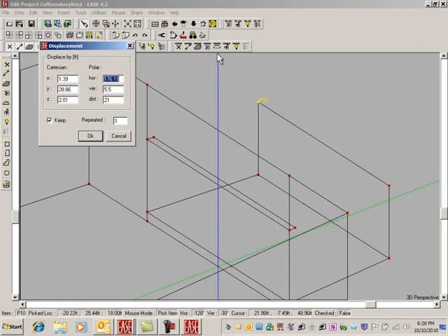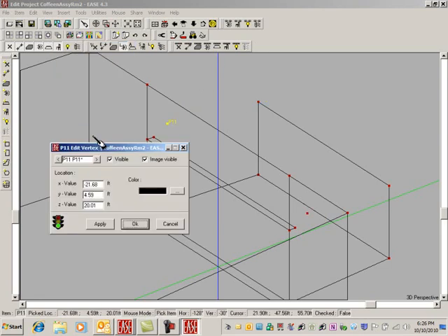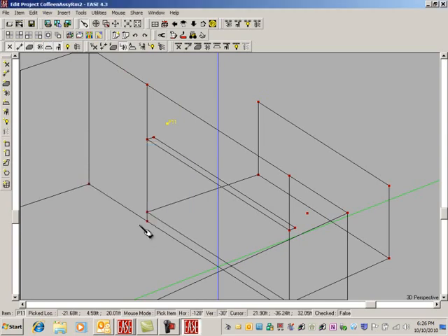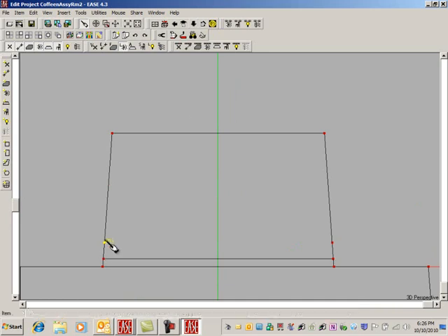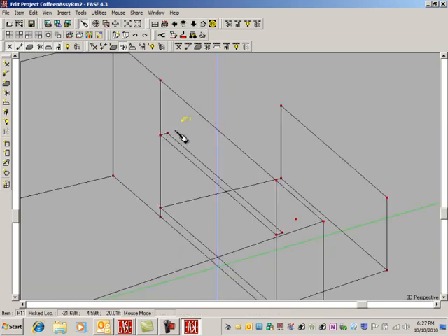But we have a window to add in here. Now, we know where that window is, and we can paste it on this wall. So, what we want to do is add a vertex in this face, because that's where it is, and if we use the top of the window closest to the proscenium, that's over 3.5 feet and up 20 feet, 17 plus 3.